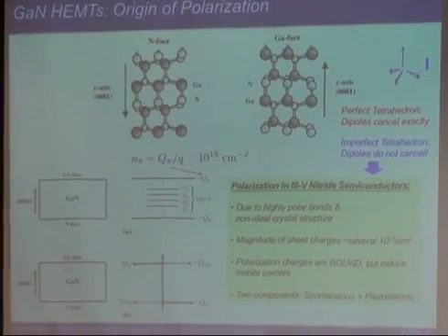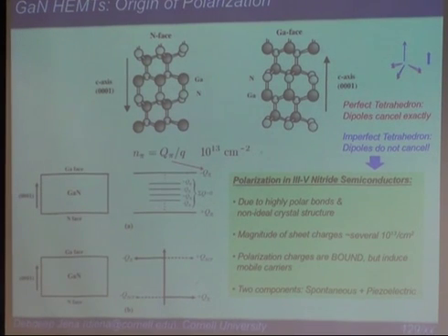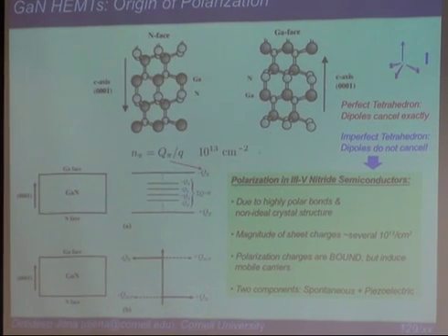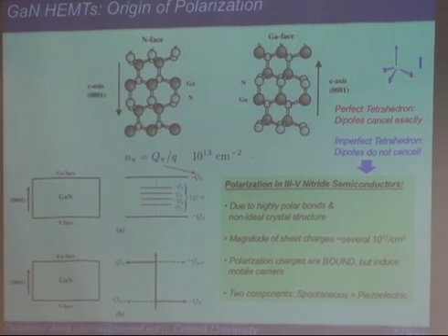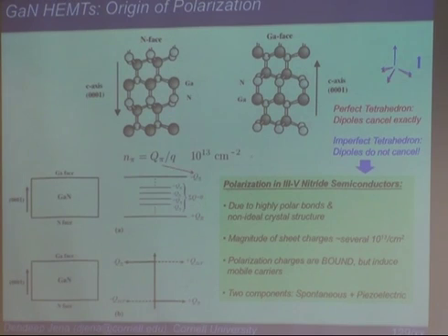Right? Remember, these charges are not charges in the bands. These are just because that electron cloud got deformed, and you're kind of saying a little heavier weight here, a little lighter weight there, slightly positively charged, slightly negatively charged compared to uniform density. That's all there is. This is not mobile charge. It's fixed charge.